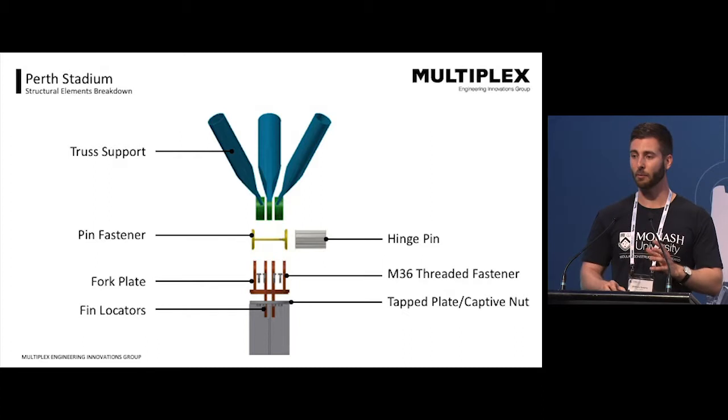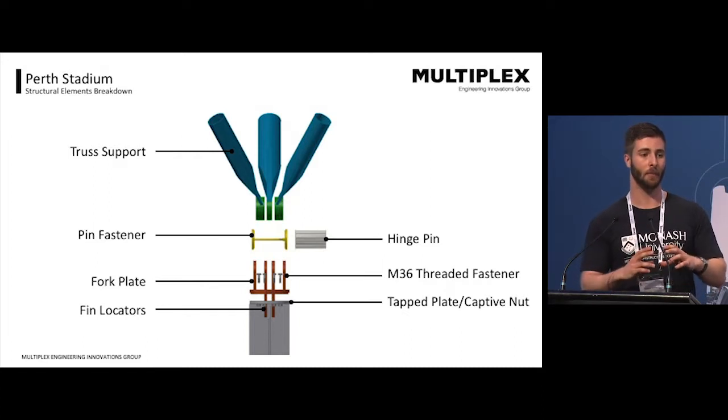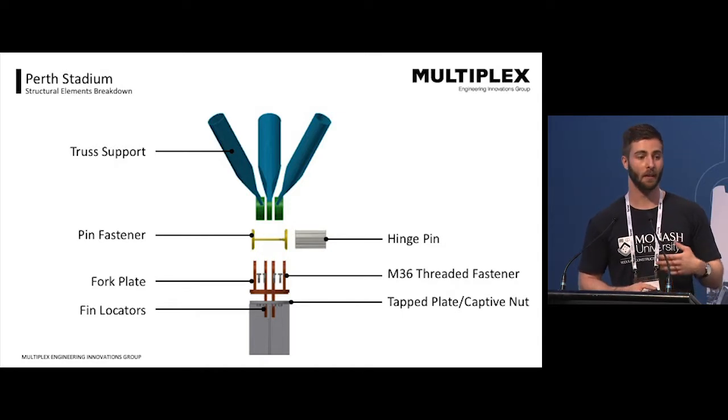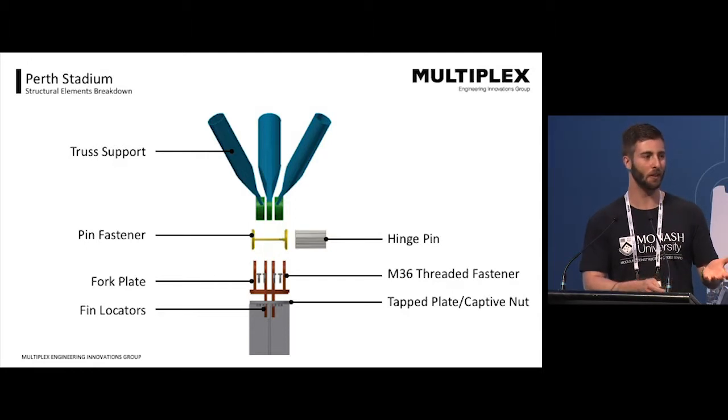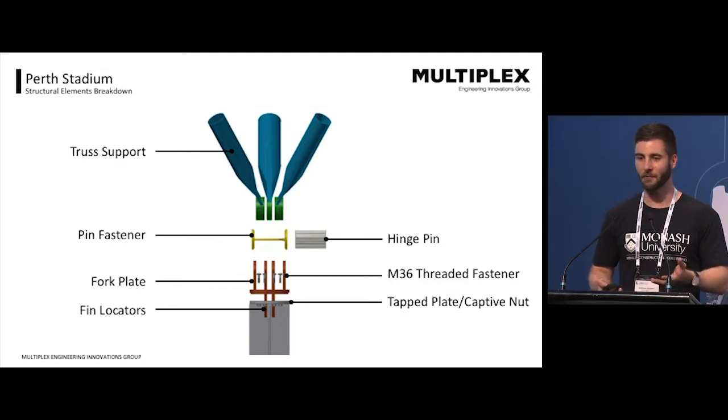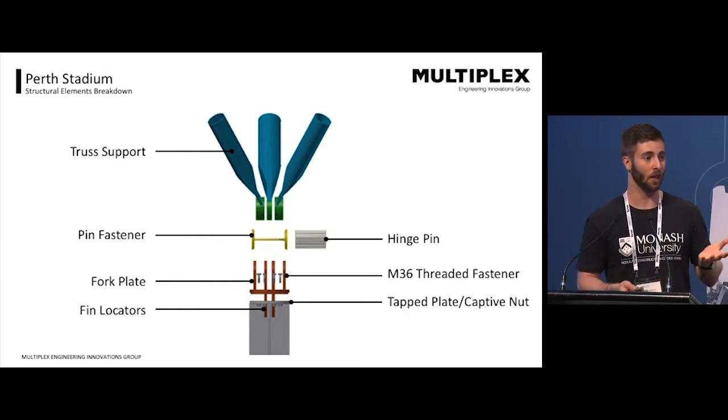We've got our 3 members, which, although they now have a ring section on the base, which allows them to rotate around our hinge, can all be prefabricated off-site. So it does bring some complexity to the design, but nothing that isn't able to be done in a controlled environment. And then for the actual installation, it's quite a simple process. We're basically threading those members with a single hinge. And to me, it seems like a pretty obvious solution, but I haven't seen anywhere else where a design like that's actually used.